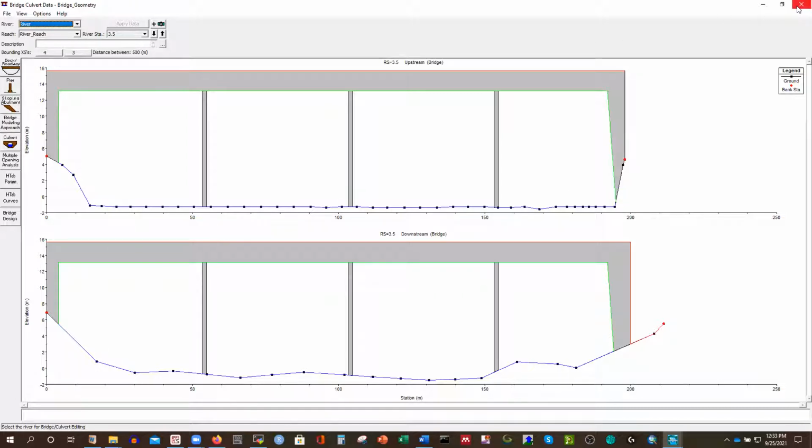So now what I have to do is calculate the scours around this bridge pier, and at the same time these are the abutments we have. There will be some abutment scour, and since we are constricting the river, the flow path, the conveyance area is reducing, so there will be another scour due to constriction. So there will be 3 different types of scours, and we'll calculate that one today.